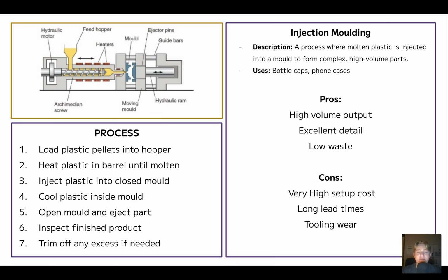What I mean by lead time is essentially the time it takes for us to go from the start of the project to the finishing point of a project, similar to sort of like our float time. And in this scenario where we're using injection molding, that is a very long time because of the difficulty of creating the molding and the tooling. And even after you've paid all that money to get the mold, it can wear out over time, which can lead to us having to replace it, which is obviously quite high cost.